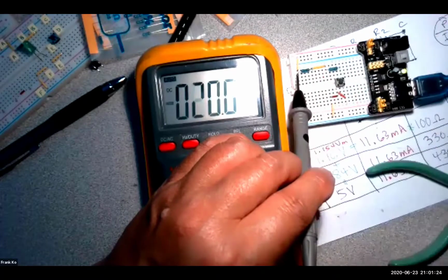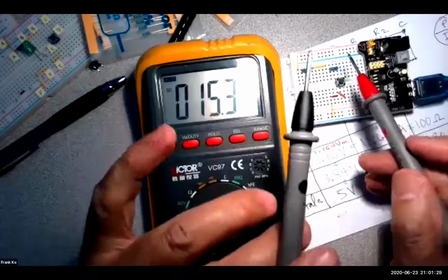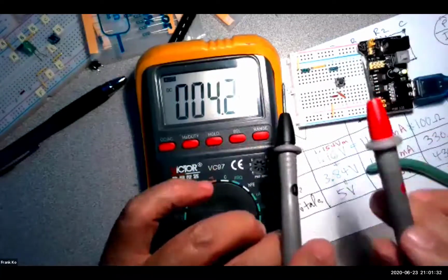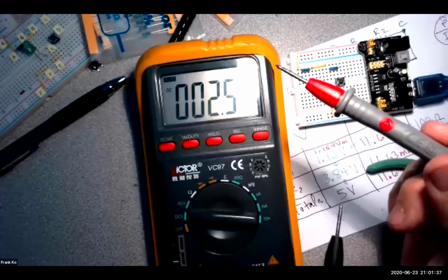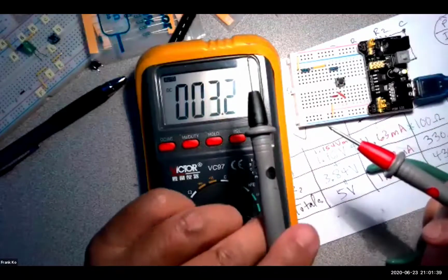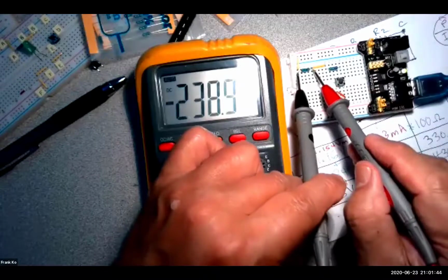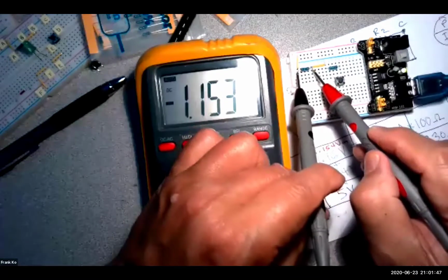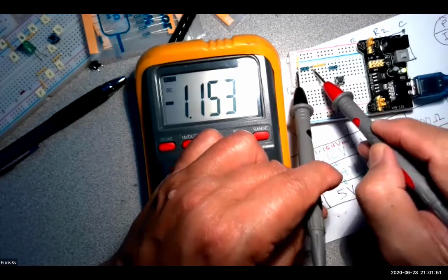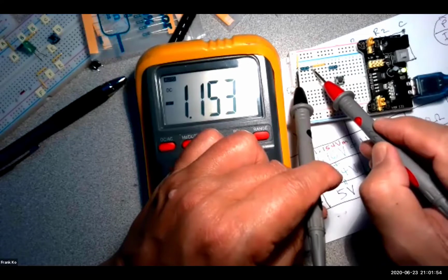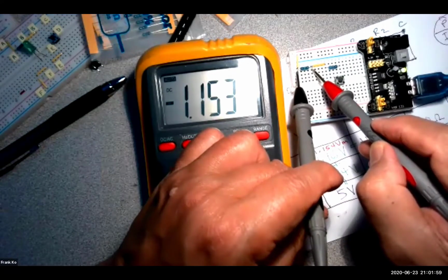The red probe is what senses the polarity when we pull it towards the black probe. Did you hear that? The polarity of what we measure is totally dependent on what color probe? The red probe, when we reference to the position of the black probe. So right now, if I put my red probe on the right side of the first resistor and my black probe on the left side of the first resistor, the red probe will see the negative side of that resistor, which is why the voltage is negative 1.153.